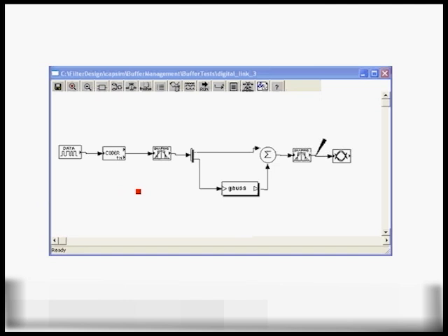But as we have shown, Capsim provides a very flexible simulation kernel, supporting flexible first-in, first-out buffers to support both synchronous and asynchronous data flow and the simulation of very complex communication systems, digital signal processing systems, or mixed analog and digital signal processing where you have to support, for example, multi-rate sampling, such as high-rate sampling on the analog side in order to model the analog, and then, of course, run the digital communication system at its natural rates.